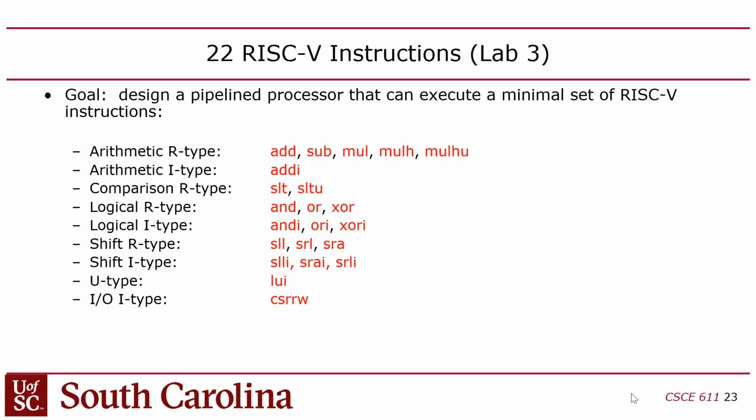Likewise, we want to be able to take data in a register and put it out on the hex displays, which will pass through your 7-segment decoders first. But we need an instruction that will trigger that transfer between the register and the 7-segment displays. We're going to use the CSRRW instruction for that.